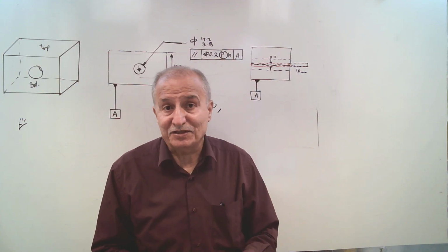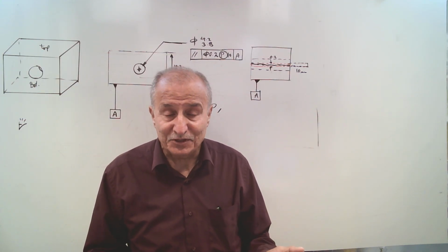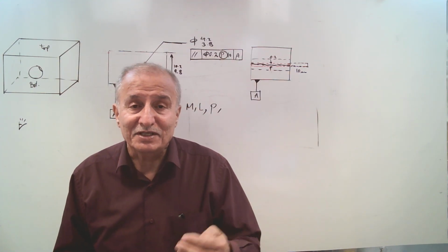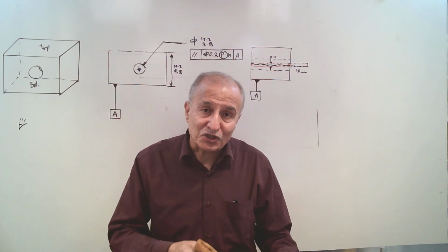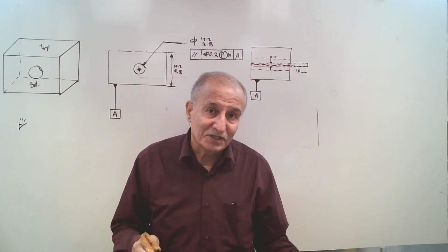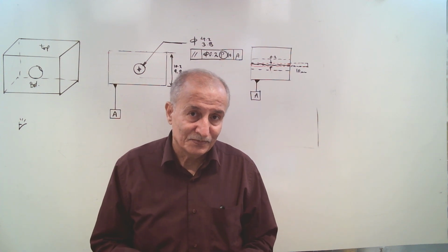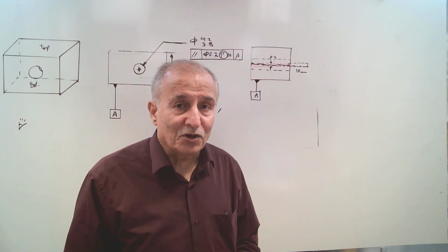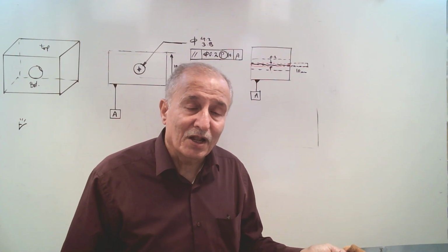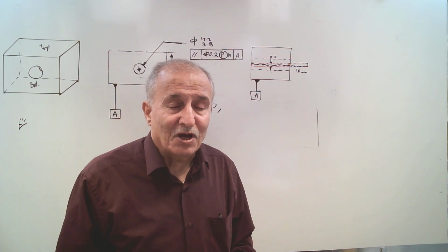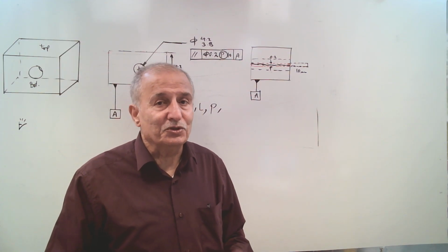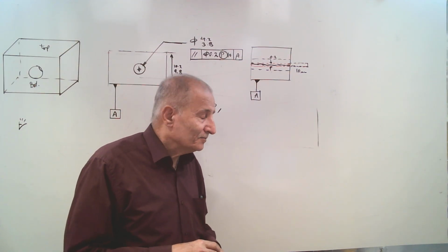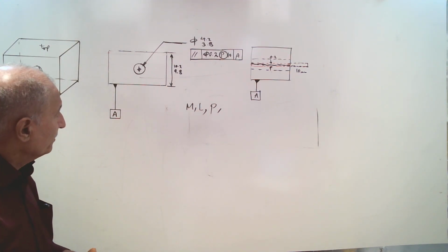For the other sizes that depart from MMC or LMC, the total geometric tolerance increases. And in this case, the size of the tolerance zone also increases and is variable. You know that for flatness and for straightness, we talked about it and we constructed the table and showed how to calculate bonus tolerance. You can return to that video about straightness and flatness with M or L modifier.